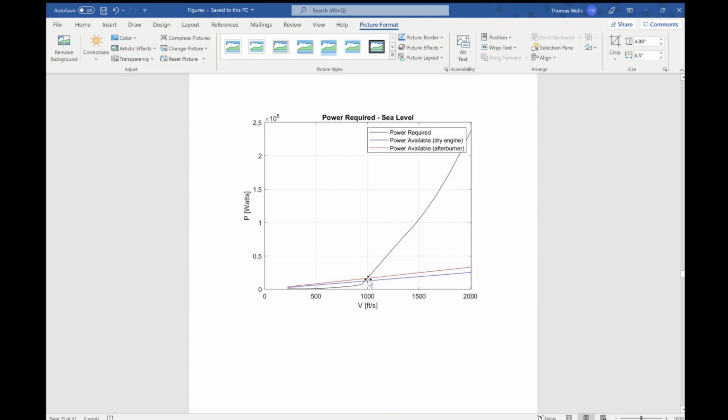per second, which at sea level corresponds to a little bit below Mach 1, so it's going to be around Mach 0.95. And we know that that's not going to be enough to meet the design criteria, especially later on when we look at the maximum Mach at 30,000 feet and 40,000 feet. So this is telling us that the aircraft is either underpowered or too draggy, or a combination of both, which is a recurring theme that we've seen as we go through and look at all of these different performance specs, as well as our aerodynamics and the propulsion model.